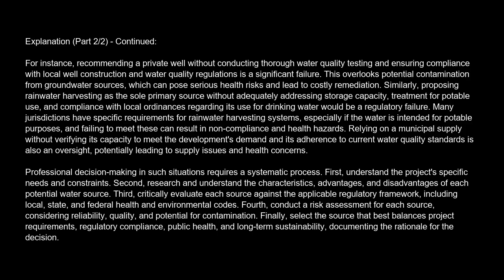Similarly, proposing rainwater harvesting as the sole primary source without adequately addressing storage capacity, treatment for potable use, and compliance with local ordinances regarding its use for drinking water would be a regulatory failure. Many jurisdictions have specific requirements for rainwater harvesting systems, especially if the water is intended for potable purposes, and failing to meet these can result in non-compliance and health hazards.